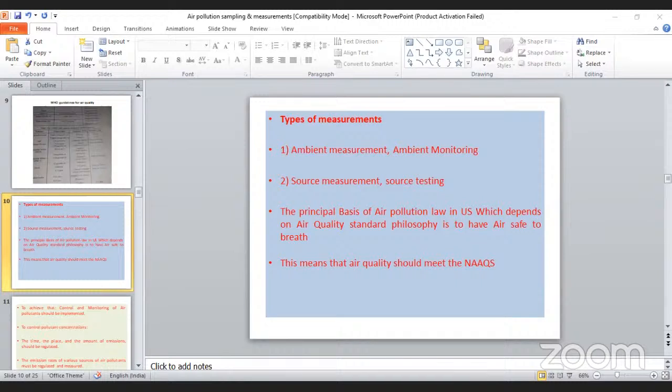An impinger bottle means it's a kind of bottle which has two mouths. One is at the top and another opening is at the side. When we want to separate liquid and gas, or soluble gas and insoluble gas, through the collection medium, some solvent must be present in the bottle. The impinger bottle looks like a round bottom flask, which has two mouths.